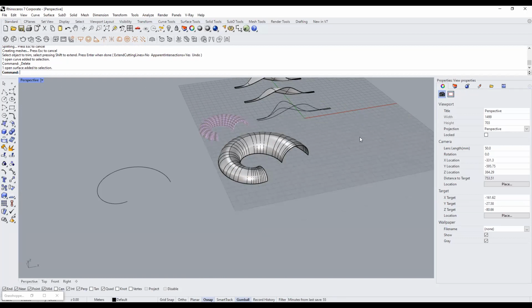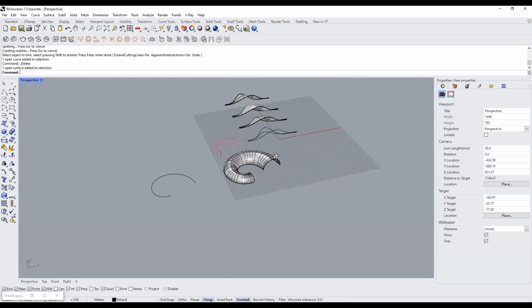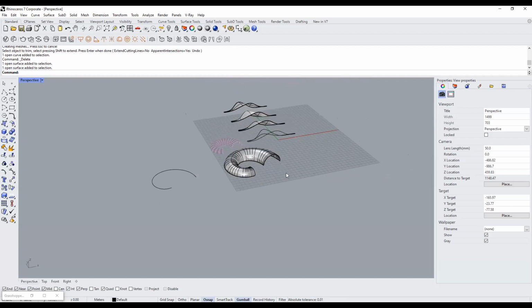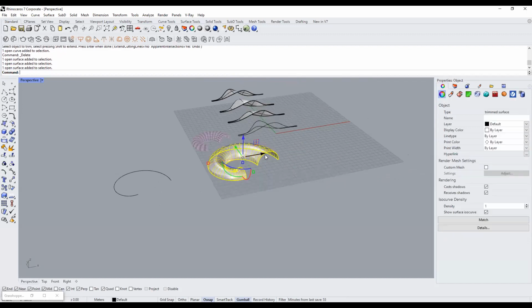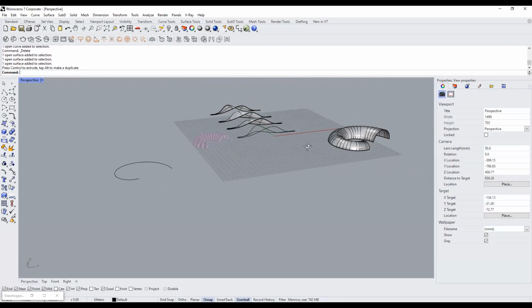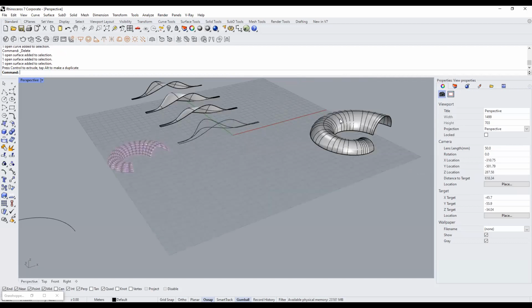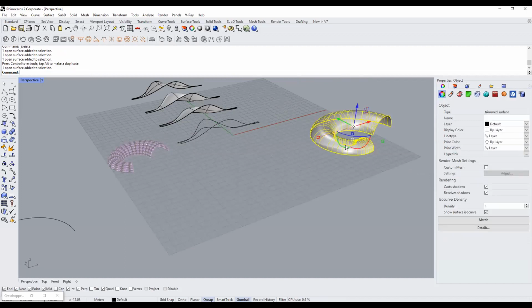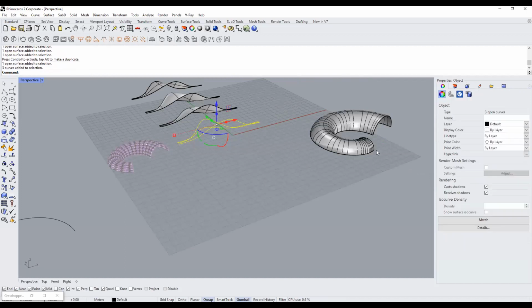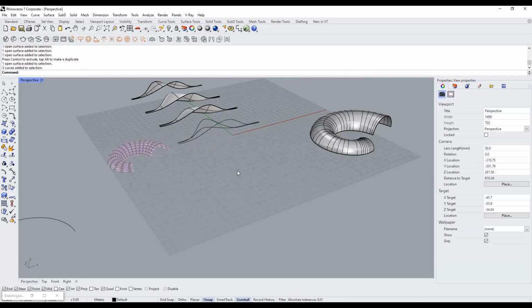So I will introduce you to Grasshopper and we will work on creating a pattern as you are seeing on my screen. Also, guys, have a surface ready if possible. I will save and share this RHINO file. You can directly use it from here. You can use any one surface that we have done. Create any surface, no restriction, either something like this or randomly through curves and Loft, and then have it ready for the next part.